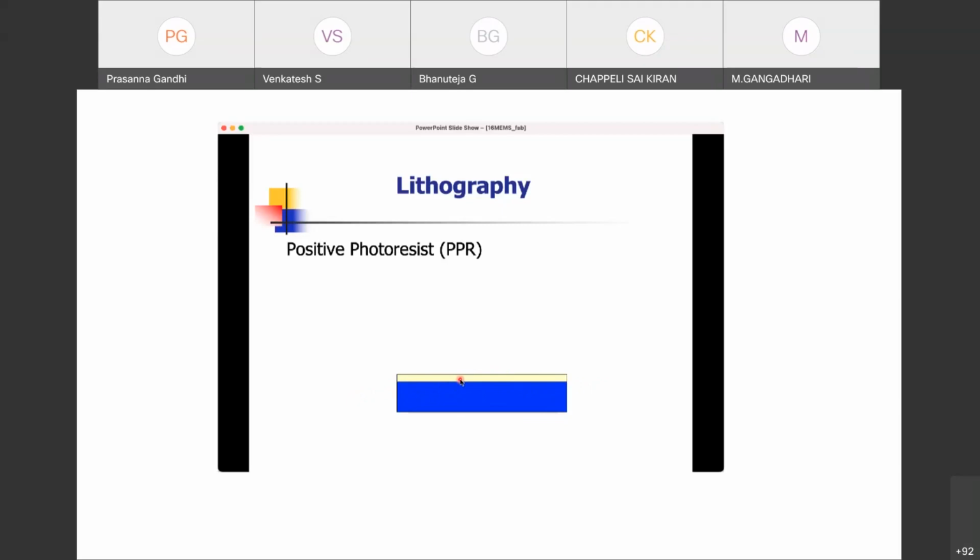Okay, there is another concept: you use a kind of mask where there is a window. Now this window need not be a physical hole. It's just that some part of the glass is coated with metal to create this mask, so the other part is transparent to the light. From this part the light can pass through, but from the other part the light cannot pass through. Typical masks are fabricated out of a glass substrate with a chromium coating on its surface. How the masks themselves are fabricated, we'll see later. There are different processes to do that.